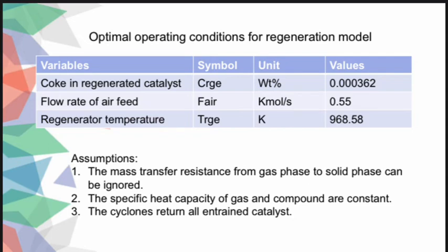A few observations have been made. At higher temperatures of more than 1300 Fahrenheit or more than 700 degrees Celsius, the burning rate is very high. Oxygen availability limits the burning rate through the small size of the fluid cracking catalyst, which eliminates or minimizes diffusion as a reaction barrier at normal regenerator temperatures.